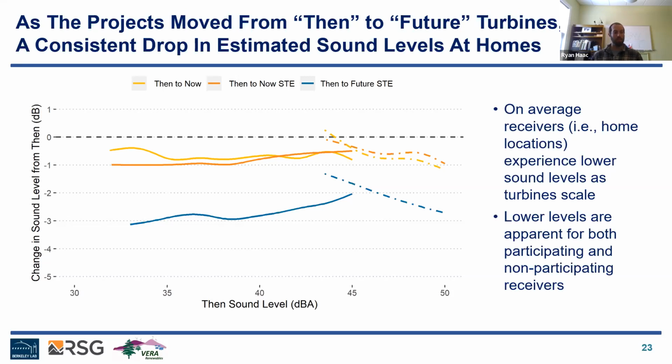But once you have a different sound generating mechanism through amplitude modulation, that's kind of stepping around those serrated trailing edges, because amplitude modulation is not trailing edge noise. There could be some concerns for sound levels similar to turbines without serrated trailing edges, for example. So it's certainly something to keep an eye on with larger turbines.